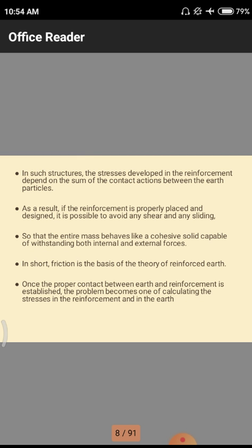As a result, the reinforcement must be properly placed and designed. Properly placed means that from a particular endpoint, we need to give some quantity of distance. Likewise, here also we have to maintain some reinforcement details in the structure. Otherwise, due to an irregular pattern, stresses are not transferred easily. Some places will absorb a huge amount of stress, some places will have less stress distribution. Due to this there may be some failure, or the structural span will decrease.